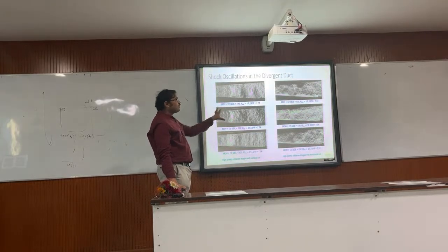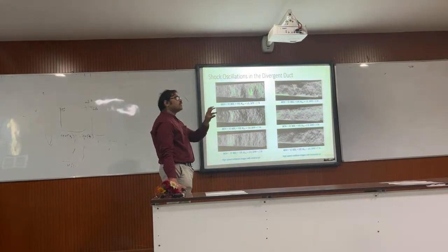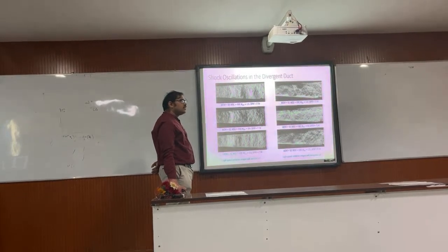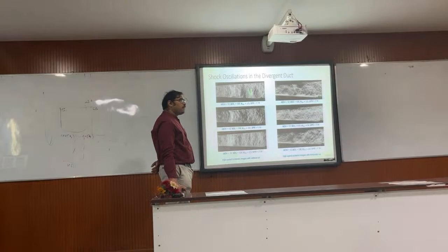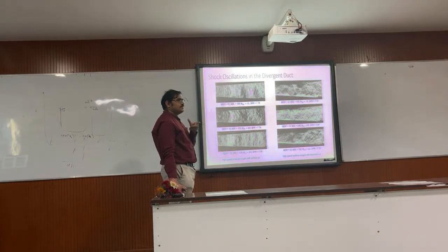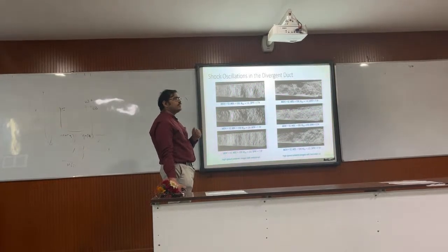Here I just wanted to tell that we are working to suppress the unsteadiness. But you are bleeding from the ramp. I've done some work where I bled from the sides, so it becomes more two-dimensional. Here the flow would be more three-dimensional, because you have asymmetry. Yes, so here what we have introduced is slots. Slot bleed, not a whole bleed.